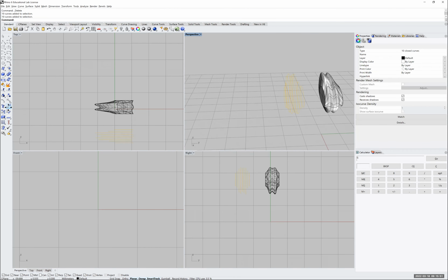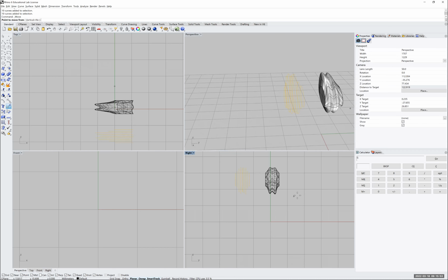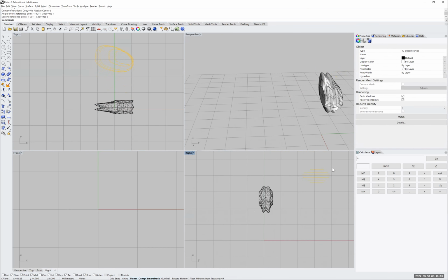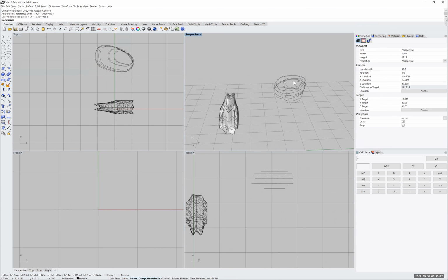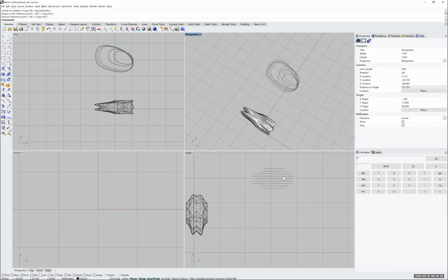So I'm going to go to my rotate icon. Sorry, I clicked on move. This is my rotate icon. And I'm going to go to the right side just so I don't snap to something that messes things up. And I want this, I'm clicking again on my shift button. I want this axis to be moved so that it is along the horizontal line. And you can see that these curves are now right here. If I look there, they're flat on a surface.